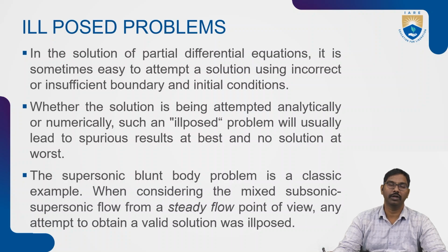If we define boundary conditions that do not match the behavior of the equation, it may lead to divergence of the solution. We cannot get the correct solution, or the numerical iterative method cannot proceed for further iterations.